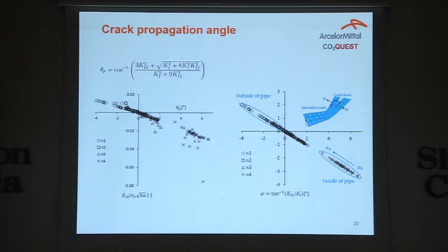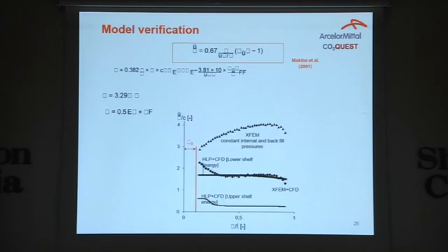And here is inside the pipe, and here is outside of the pipe. We see that the maximum and minimum deflection, or crack propagation angle, is limited. So there is no risk of mixed mode crack propagation. But the crack will be twisted at some certain points, because we have positive and negative stresses at the crack tip.